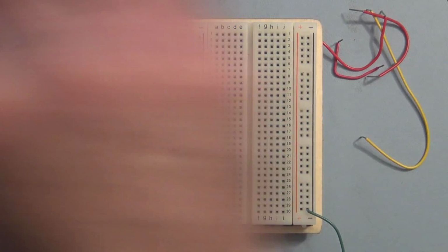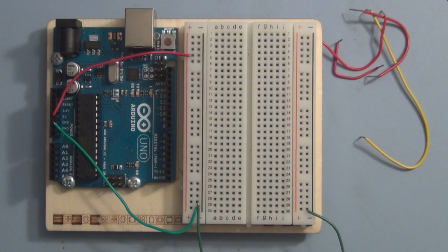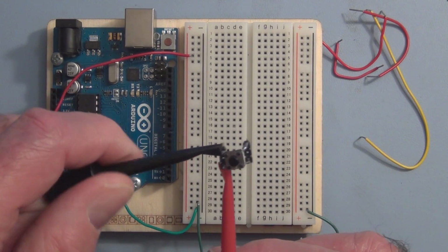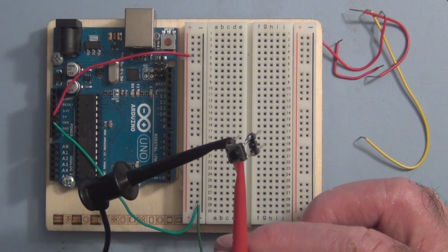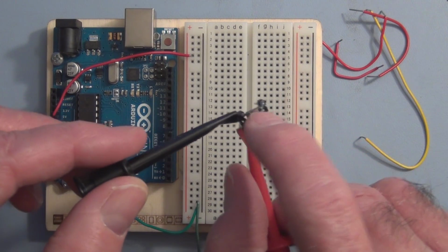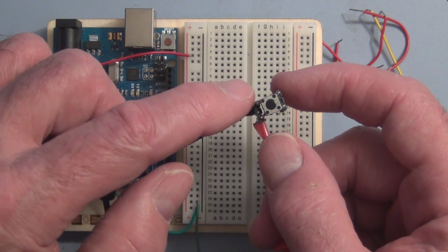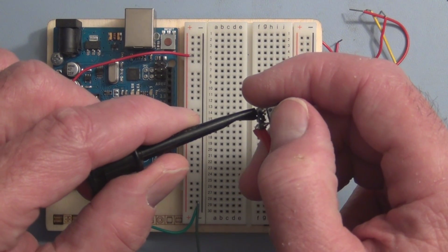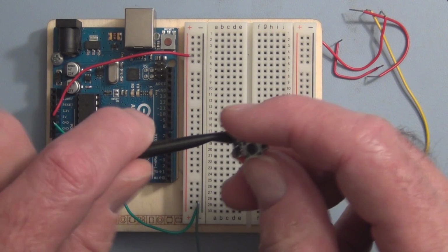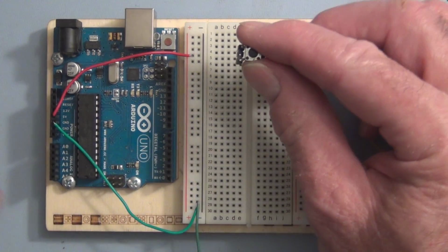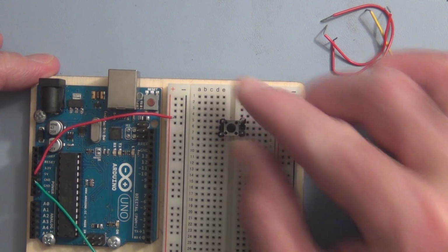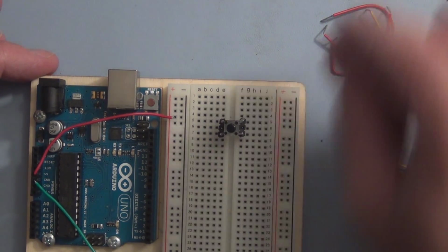If I left my meter on, I have to make sure I orient this switch correctly. If I measure here and put my meter on the buzzer for continuity, when I press, this will buzz, and I'm shorting out these two connections, connecting one side to the other. So that's how I want that to be oriented. I'm going to put that up here. I'm just going across the channel here, but I'm only going to use this one side.